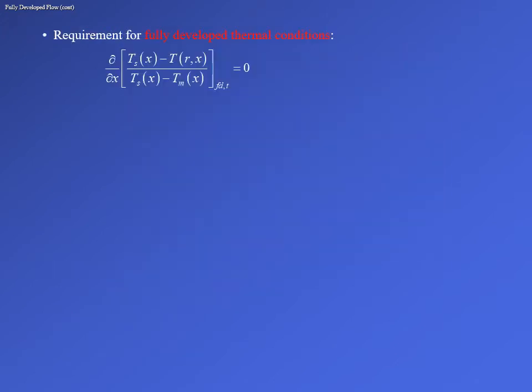Okay. But we are more interested in the heat transfer ideas. So as I said earlier, in the fully developed temperature region, it is not true that del T by del X is 0, like you had in hydrodynamics where del U by del X was 0. So then what is it that does not change with X? What we see is that this quantity, which is the scaled temperature, does not change with X in the fully developed region.